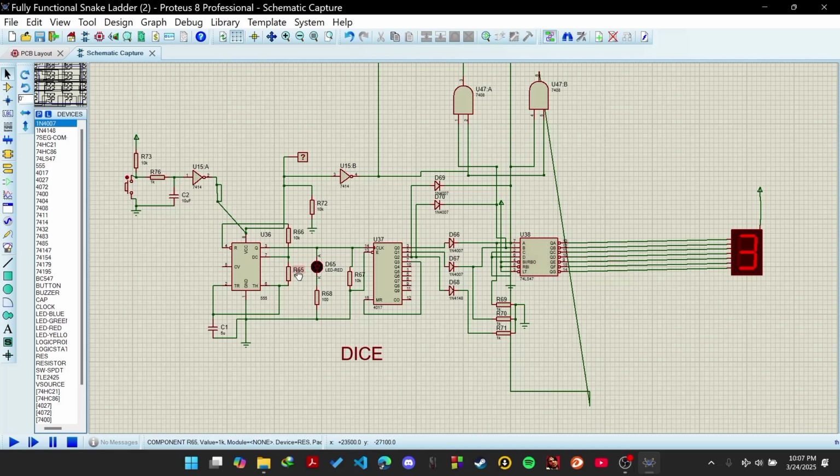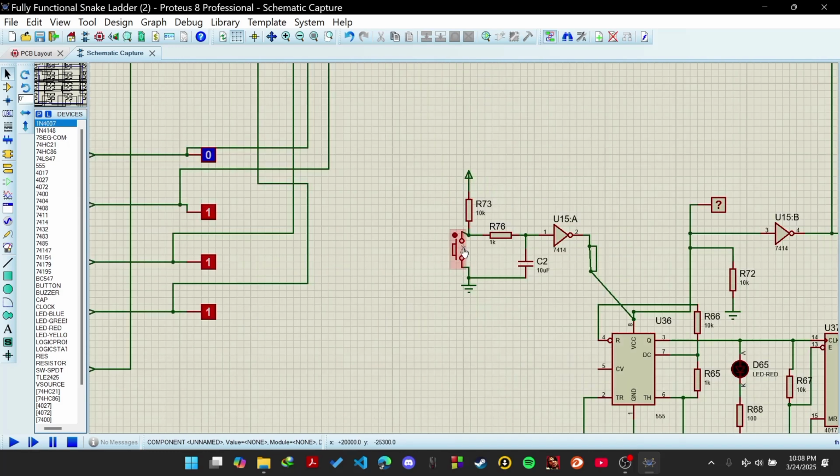The switch we used in this module is not an ordinary switch. If we were to implement this push button physically, we would need debouncing due to mechanical vibrations of the metal contacts, which could cause false triggering of the dice roll. To eliminate this, a debouncing circuit is used with a Schmitt trigger and a low-pass filter. To achieve smooth switching,